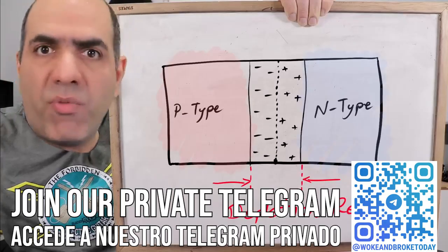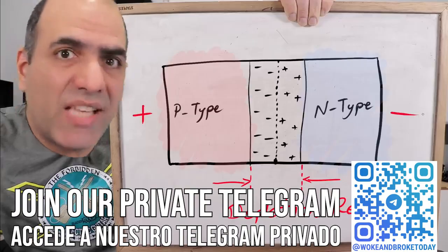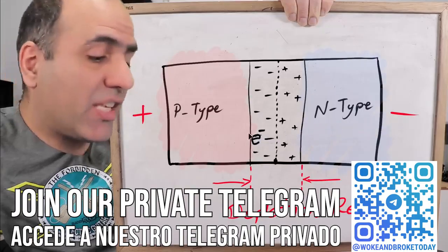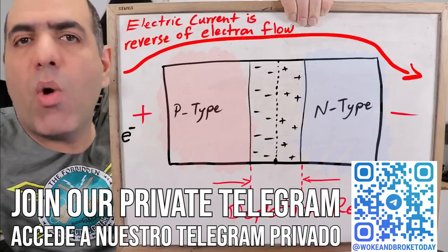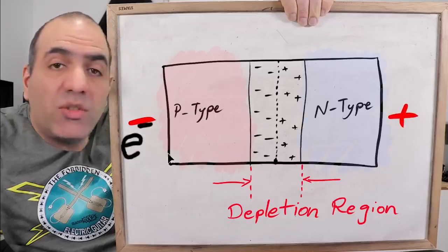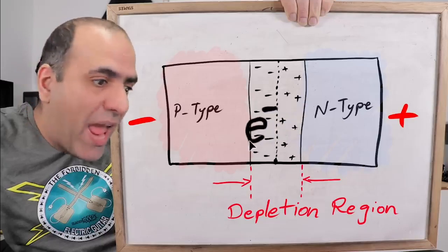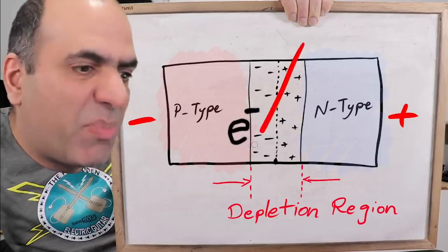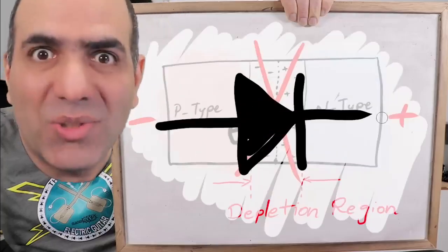So this means if we decide to put a positive voltage on the p side and suck electrons out, p gladly takes electrons from n and the negative terminal, and current flows with low effort. But if we flip the voltage across the p-n junction and try to force electrons into p, it won't want to pass electrons into n. That's not their deal. The p-n junction blocks the electric current. So we have a diode.